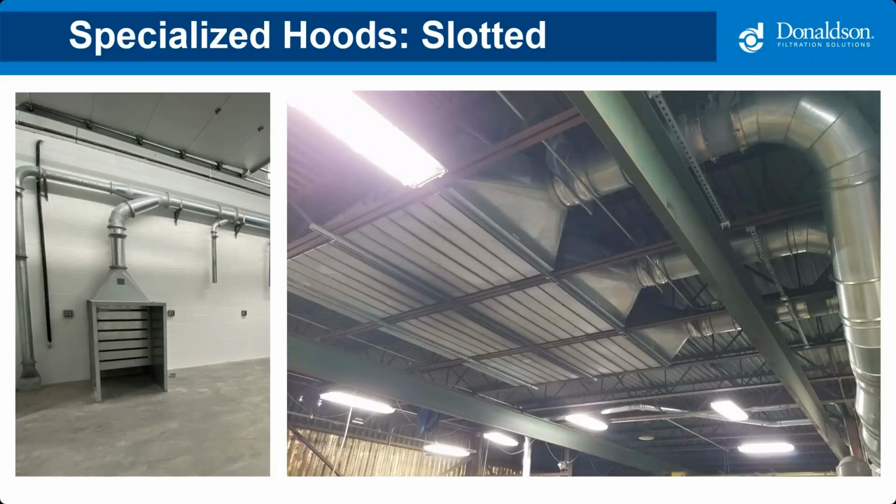And it has the same effect as these slotted hoods, where it's going to capture the weld fume as it comes up, but then around the perimeter, there's a high velocity area to pull the dust into the hood. But since it's such a small area, such a small width, you can capture a big area of welding using a very small amount of air, which again keeps smaller duct, smaller dust collector, smaller fan, etc.